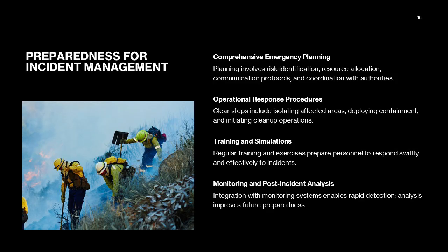Emergency response planning is critical for minimizing the impact of pipeline incidents such as leaks, ruptures, or explosions. A comprehensive plan includes risk identification, resource allocation, communication protocols, and coordination with local authorities. Operators must establish clear procedures for isolating affected sections, deploying containment measures, and initiating cleanup operations.